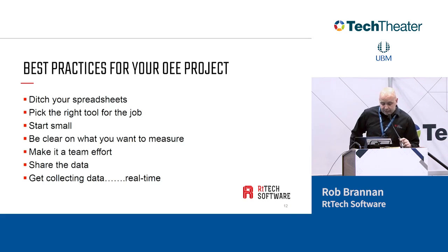And then for me, it's collecting the data, but definitely real time. I can't emphasise that enough. If you're at the early stages of deploying OEE, definitely do it manually to begin with, but don't hold on to your spreadsheets too long. They'll get too overgrown and very, very hard to manage. So take the plunge and move to a real-time system as soon as you can.